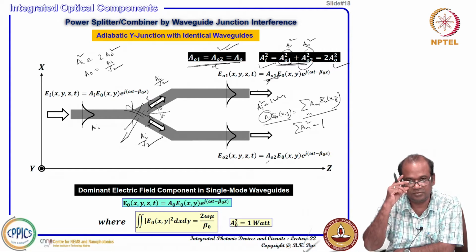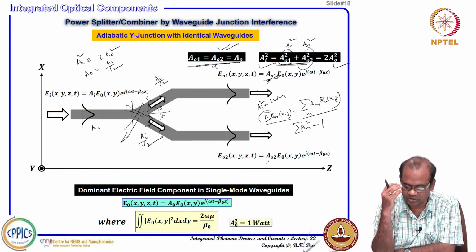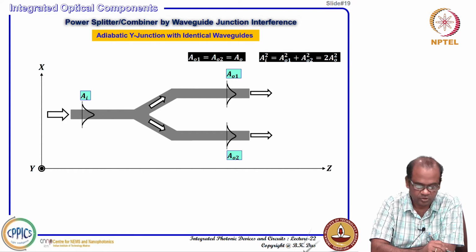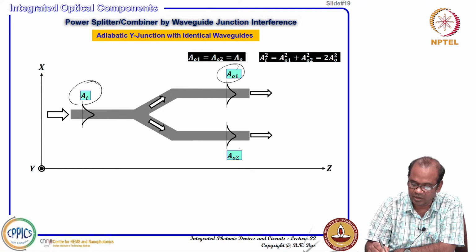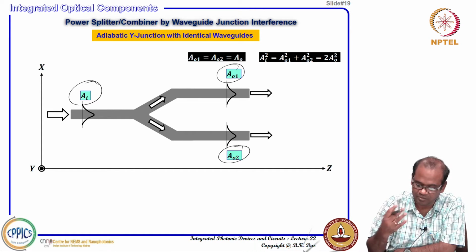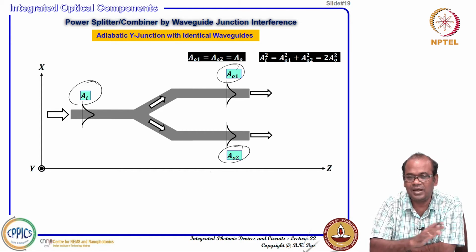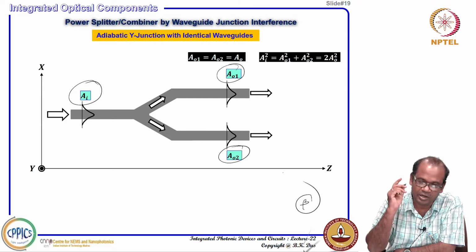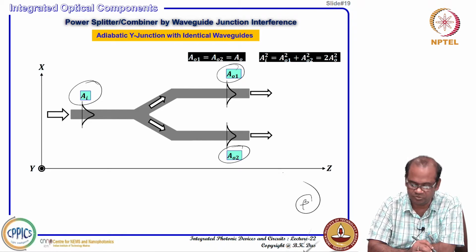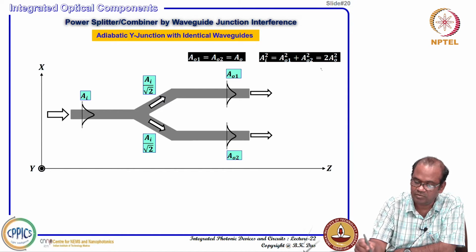This is possible to design. A loss would be created almost like a waveguide loss type of situation, so you can assume that. Now, I have written A_I, A_O1, A_O2, that means output amplitude 1, output amplitude 2. I forgot everything about the xy dependent profile. The only thing I know is that they are identical waveguides. Since they are identical waveguides, I am not considering what beta is involved. Anytime needed, I know the beta value, so I can take that help for further calculation. According to our concept, this is what we derived.